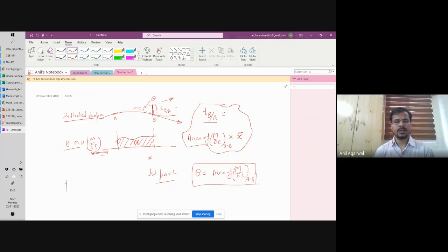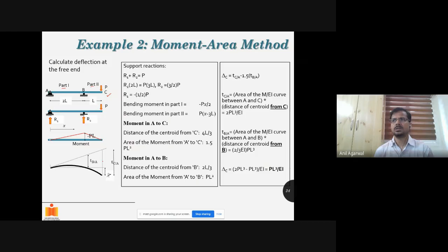Okay, so if I had a cantilever and a beam extending from it, and whatever type of loads are acting, if I could get the bending moment diagram, I knew that after deflection the beam will deflect this way, and I already knew the slope at this point. This was 0. Okay, the slope at this support is 0. Correct? So with respect to that, if I calculate the deflection, it will be directly given to me by this method, and it will be the actual deflection too. But in this particular case, that is not directly applicable. Anyway, so let me go step by step.